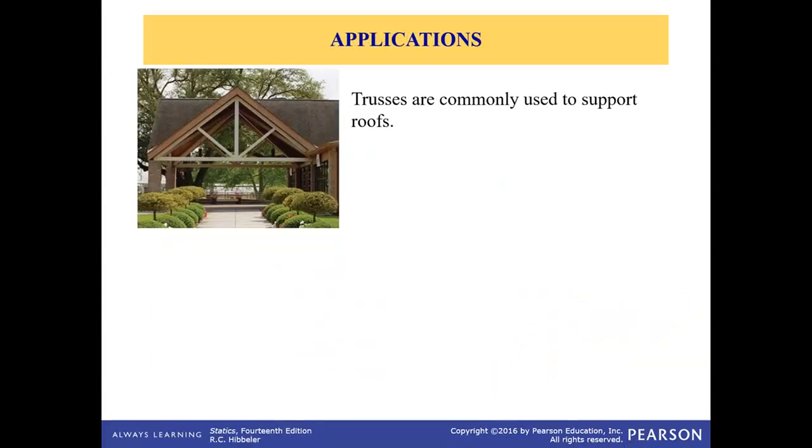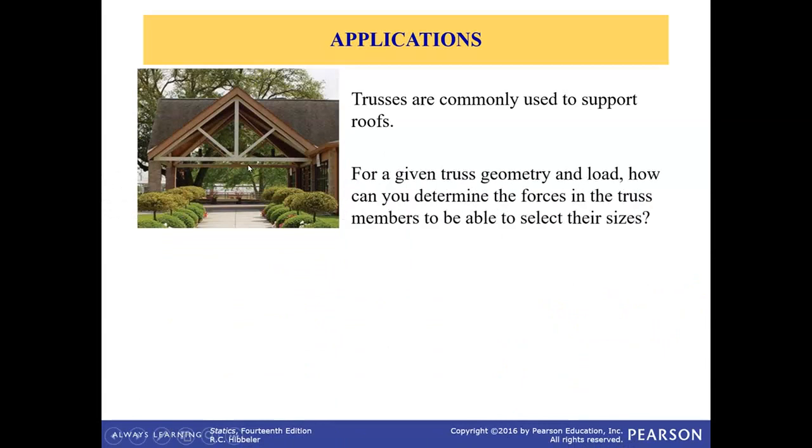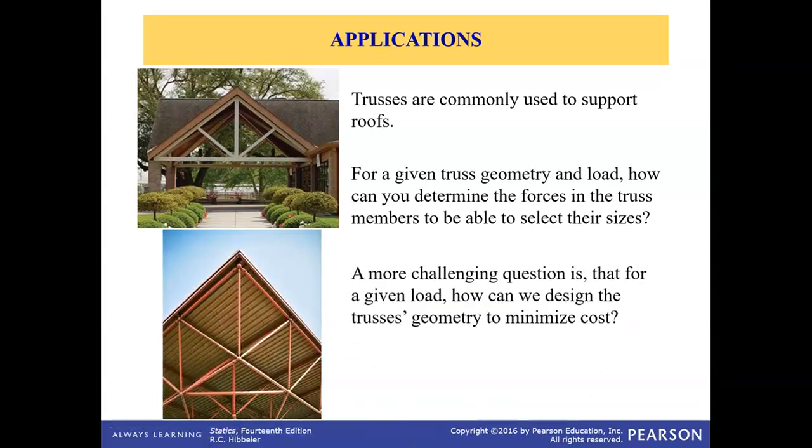Application: trusses are commonly used to support roofs, as you can see here. Now, for a given truss geometry and the load, how can we determine the forces in the truss members so that we can size them? So, if we have been given truss and externally applied load at different joints of the truss, and we would like to calculate the forces within each member of the truss, then we can apply truss force analysis. However, a more challenging problem is that if we have been given the load that the truss should carry, how can we design the truss's geometry to minimize the cost? And there are multiple options available to design the truss geometry for the given loading condition,